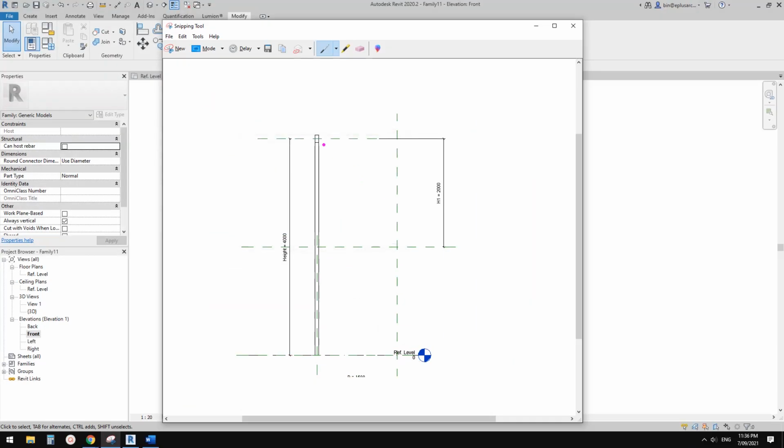Now these are the braces in the X shape. Currently when it's fully open, it's roughly 1.5 meter. And then this looks like roughly 2 meter. In this triangular shape with a 90° angle, we know we can get 3, 4, 5, which means this one will be 2.5 meter. The length of this one will not change.